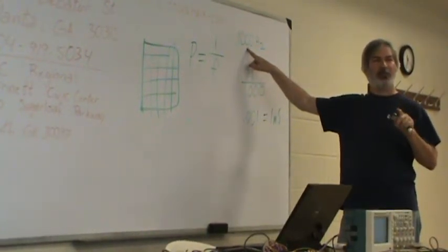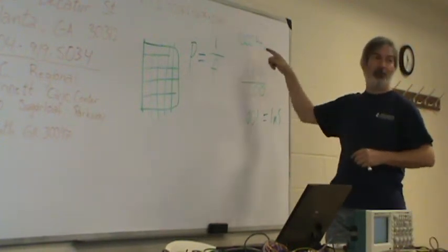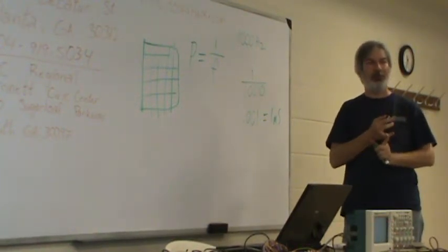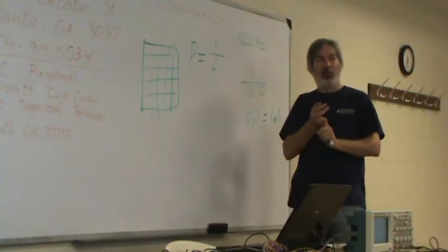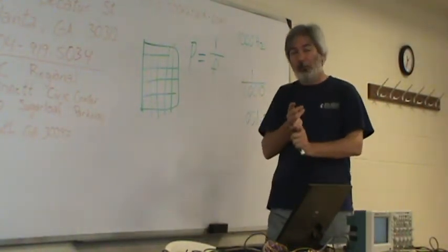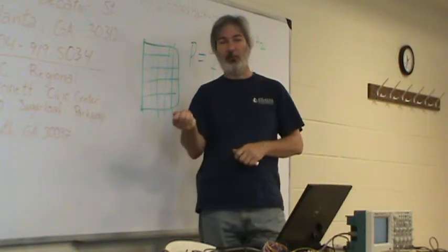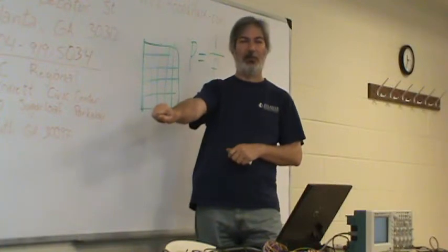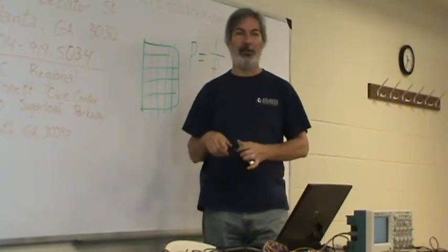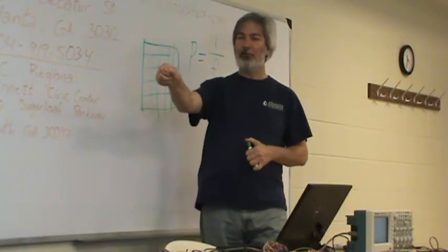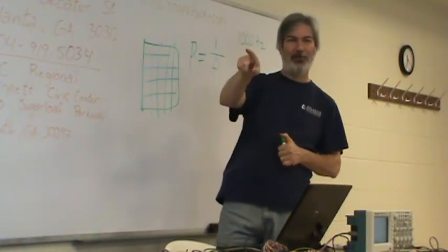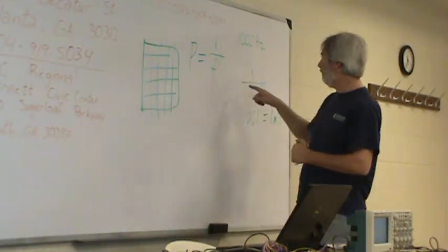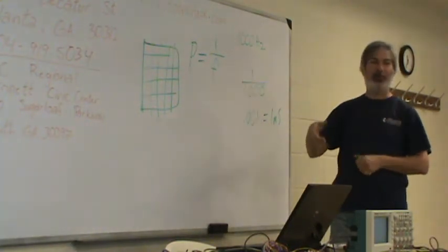What she's asking is, where do I get this 1,000 hertz that I'm looking for to start with? She doesn't know the period and she doesn't know the frequency. How does she know? Well, hopefully you'll start off knowing, but if not, Dale's method works perfectly. You start with your scope at the highest and start turning the time base down until a signal shows up. In the old days, we would look at the sweep rate and the divisions on the scope, count it out, find the period, and run it through the formula, and we'd know the frequency. Now you just push your button, and it just tells you.